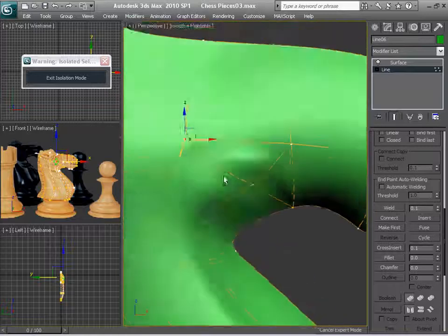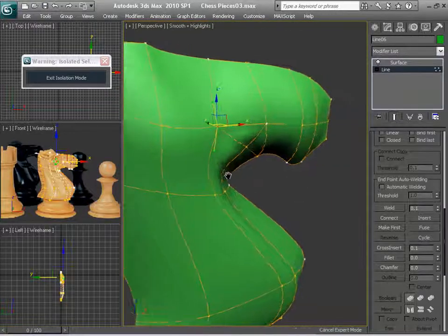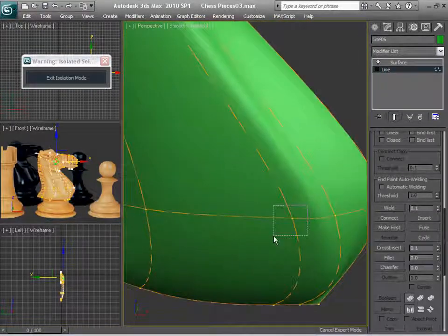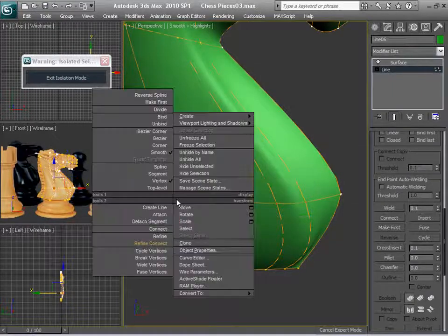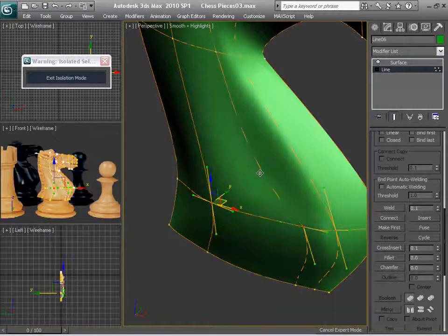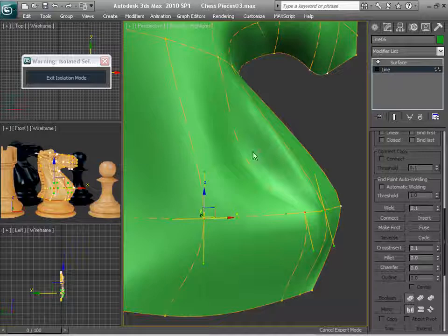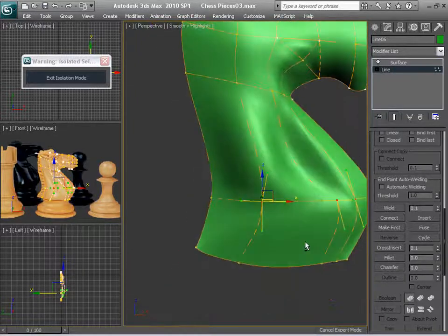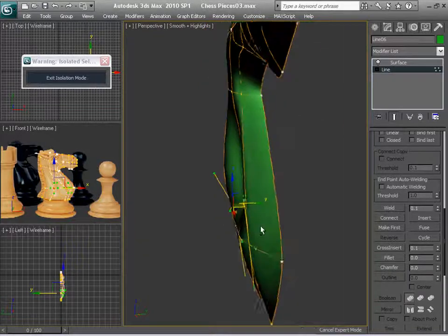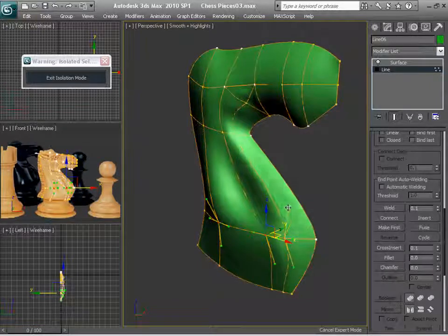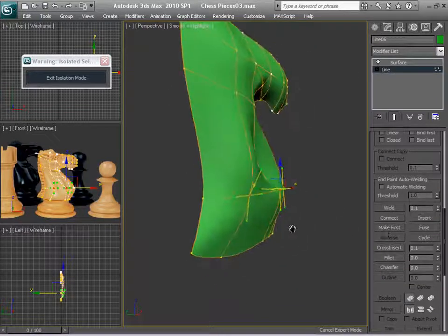When we finish creating the shape that we want, I'm going to show you how we can convert this to the other side. And this is where the handles come in handy. Look at this. We're going to grab these 3 vertices and convert them to Bezier corners. And now, when you push one of the handles in, you create this pushed-in surface. And that is exactly what we were looking for, because we want some parts of the mesh to be pushed in and some others to be pushed out. And as you can see, that is exactly what we needed.